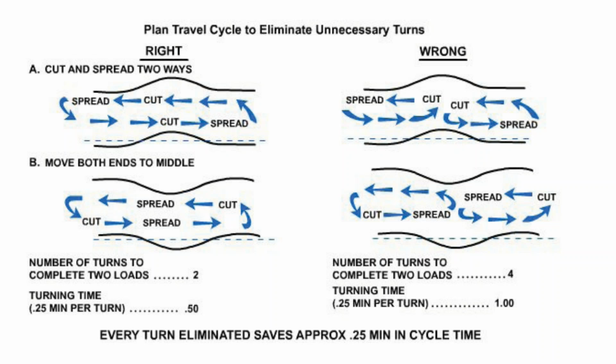You know, we've talked about dozers, and dozers are expensive pieces of equipment. The D9s, D8s we've talked about, they're in the $250,000 range, $150,000 range. They're not cheap, but they look cheap if you compare them to scrapers. A 631K, which is a common scraper that requires a push cat that you will see in many locations, has a purchase price of about $2.7 million. And so you don't get production unless you've got 10 or 12 of them. So think of the capital investment. You have $27 million worth of scrapers.